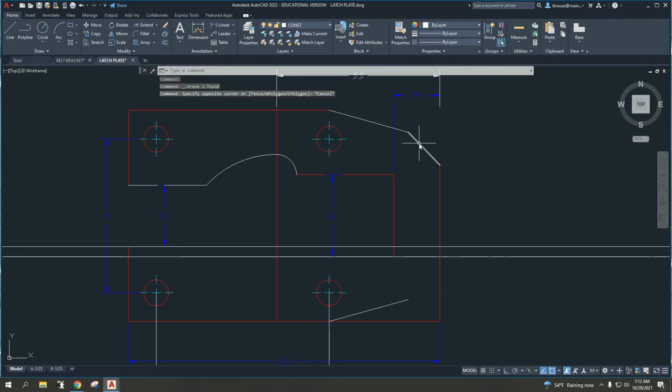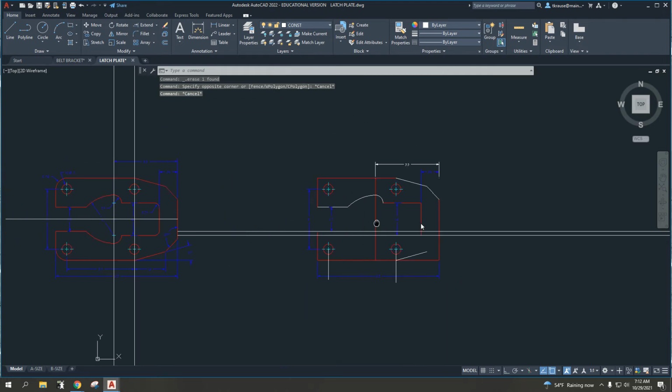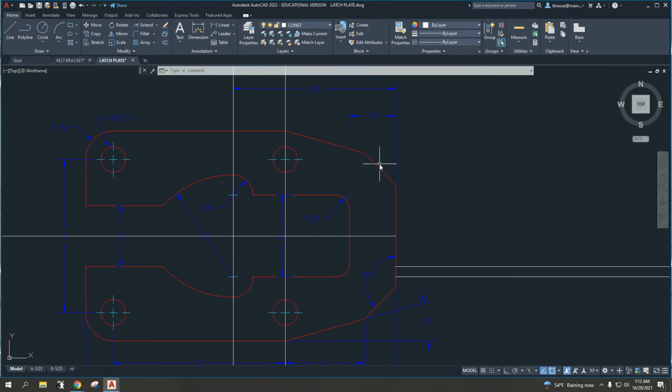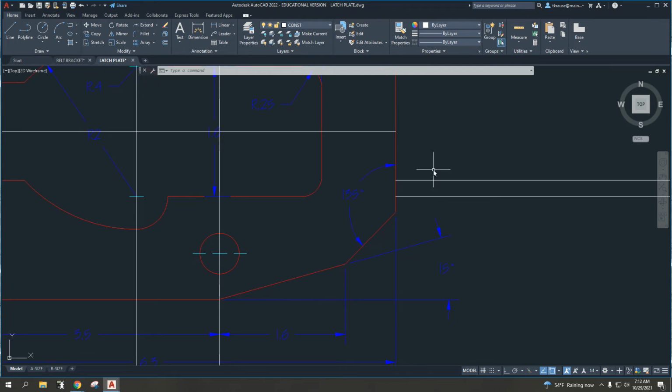And now I have to figure out how to draw this line. And this is one, and again, it's going to create a challenge for you. I'm going to show you how to do it down here, but up on the top end, with the one I already did, you're going to have to really pay attention to the fact that to the right, horizontal is 0, and we go counterclockwise. So perfectly vertical is 90, 180 is the opposite direction, so horizontal to the left, 270 straight down or opposite of 90. And if you don't use the mirror command, you'll have to actually do some math to figure out angles. And here's where that math comes in.